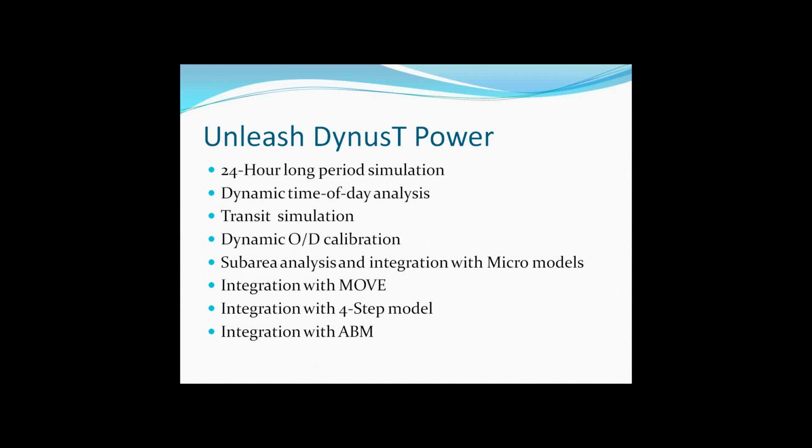DynusT can create a dynamic, more realistic travel time scheme, and this information can be fed back to the four-step model. I know some people want to stick with their four-step model framework but don't like the static travel time scheme, so they can use this approach to improve their existing four-step model. Ultimately, you would like to integrate activity-based models with DTA. This effort is already under development, and Dr. Chu already has a project on this part.